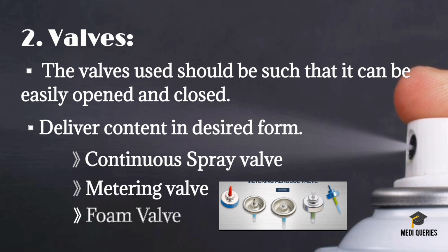By using the continuous spray valves, the medicament is expelled continuously as long as pressure is applied on the actuator. But by using the metering valves, only a defined quantity of the medicament is expelled when the actuator is pressed. And if the content of the aerosol is required to come out in the form of a ball of foam, a foam valve is used. So these are the different valve systems generally preferred for the manufacturing of the containers for the aerosols.